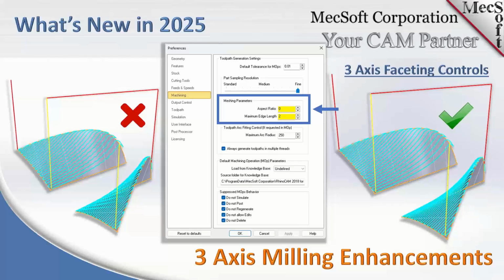You're going to get a very regular mesh on the surface. And then you can also control the minimum edge length to control the number of triangles, or facets, you're getting in the mesh. We've done some heuristic testing on it, and we have some data on the right things to set up, and we can share that with the customers. The edge length is obviously dependent on the part size. With the aspect ratio, typically if you want regular triangles, you want to set it at 1. And when you do that, the toolpaths are quite a bit improved.